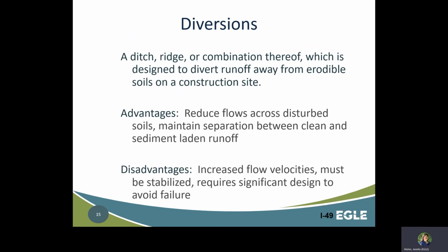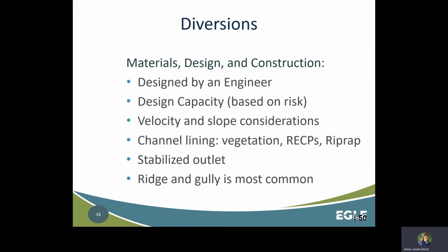On sites with steep slopes, a grade stabilization structure may be used to convey stormwater from a higher elevation to a lower elevation. At the outlet to the grade stabilization structure, riprap is commonly used in order to dissipate the energy of the water and to prevent erosion at the outflow area. Because there are many factors to consider, diversions should be designed by an engineer.